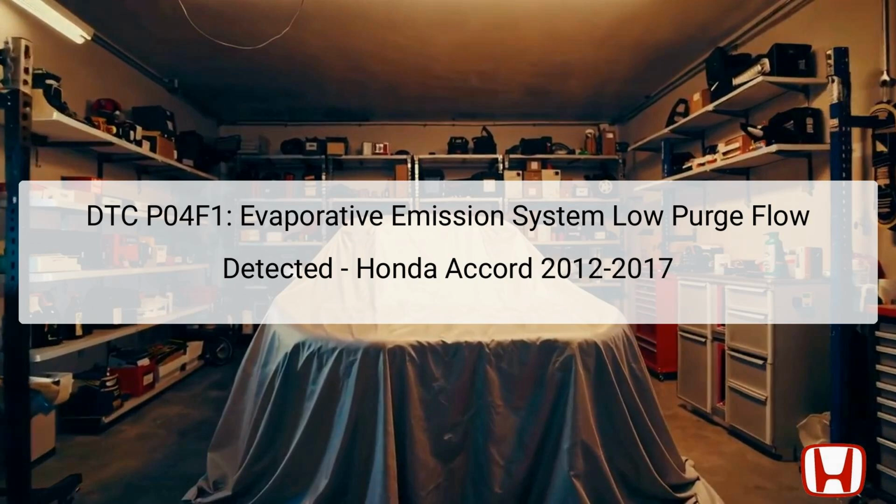The EVAP canister, typically located near the fuel tank, acts as a temporary storage unit for these vapors. The Powertrain Control Module, PCM, manages the flow of these vapors by varying the operation of the EVAP canister purge valve. When the EVAP system isn't functioning properly, it can lead to increased emissions, potential fuel leaks, and may trigger the check engine light. Understanding this code is crucial for both emissions control compliance and vehicle performance.